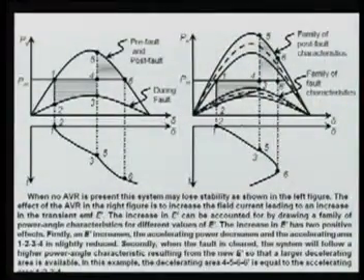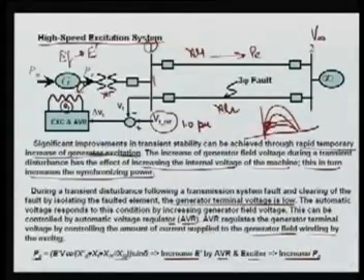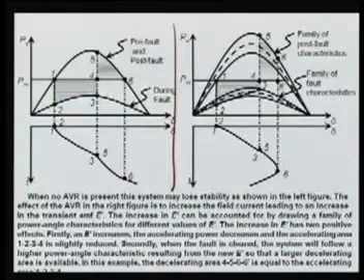Here on the left hand side you can see this graph I have shown. In this case again I am assuming the fault is there, but this line is intact after the fault is cleared, meaning this is a three-phase bus fault. The pre-fault and post-fault curve is this outer curve, meaning your impedance is not changed, lines are intact, GT is intact, and of course the generator is connected to the system.